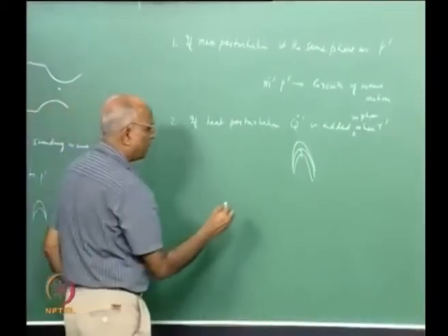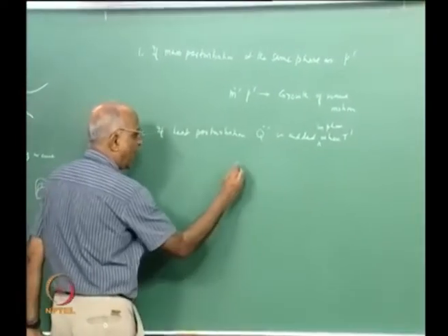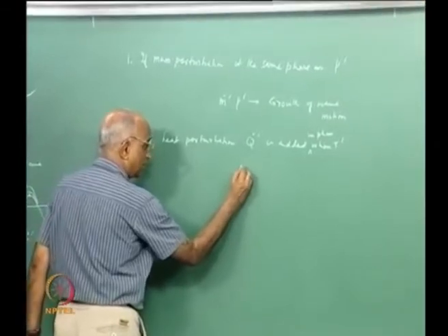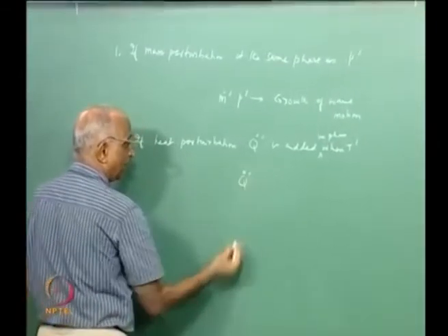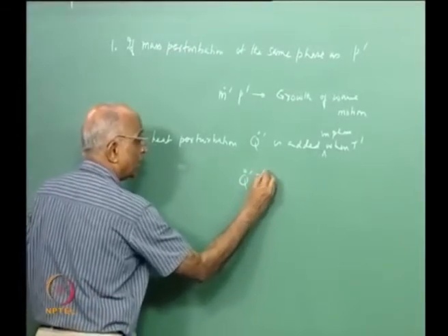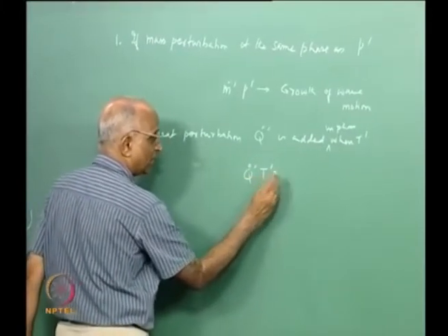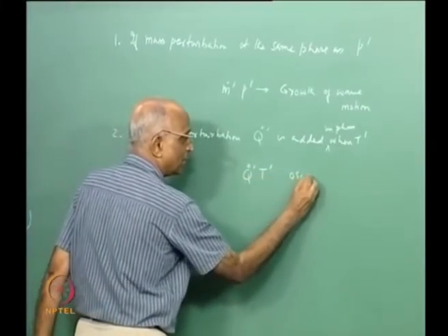Therefore my zone of interest could also be if I add heat perturbation, because in a chamber I am generating heat, I have a rate of heat release perturbation along with a temperature perturbation, and if this is in phase with this, the oscillation could increase.